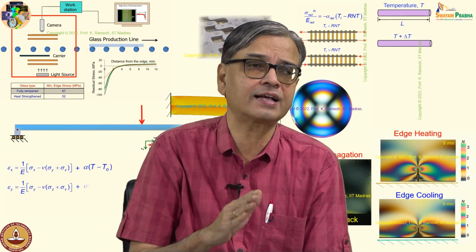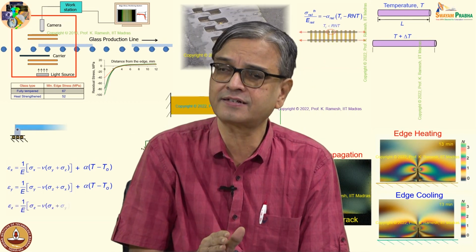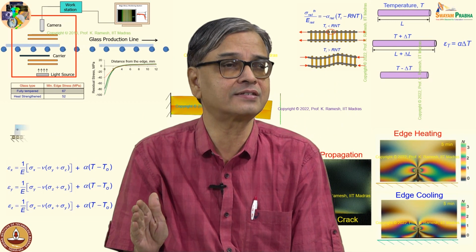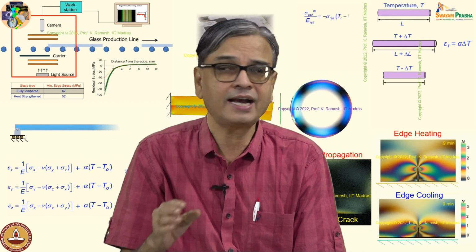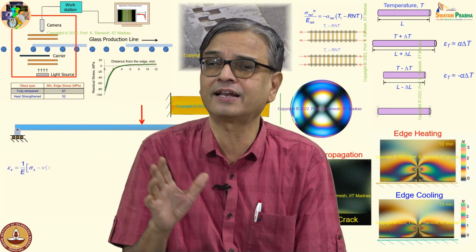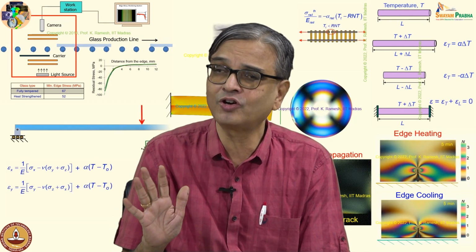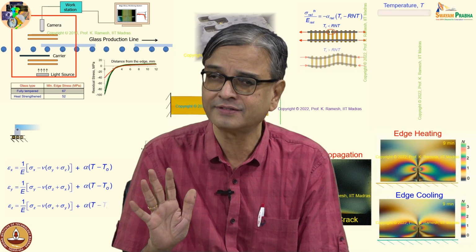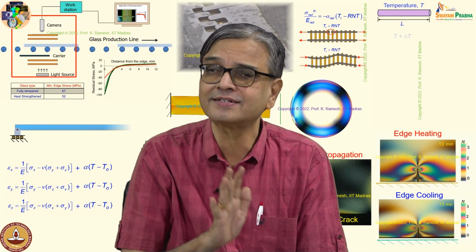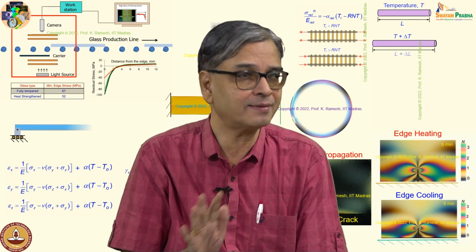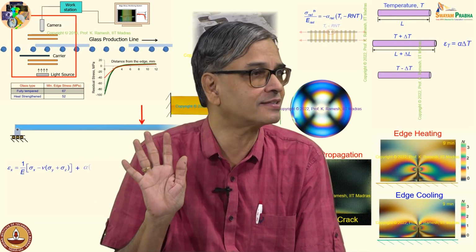In this case, mechanical stresses are introduced as well as temperature effects have to be considered, and I need to know what the final stresses developed are. And we live in the world of linear elasticity. So, solve this as two problems. One is a mechanical problem, another is a thermal problem, and finally add up the stresses. Is the idea clear? Okay.